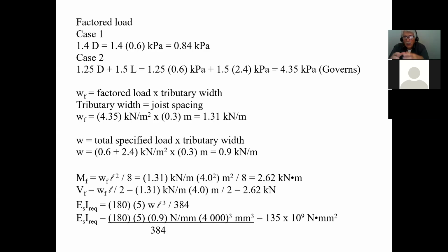Now, if there is no material susceptible to cracking, this standard requires a maximum deflection of delta equal to L over 180. So you should check both and see which one governs. But in this case, there was no material susceptible to cracking, and therefore I don't have to check the L over 360. Do you understand?